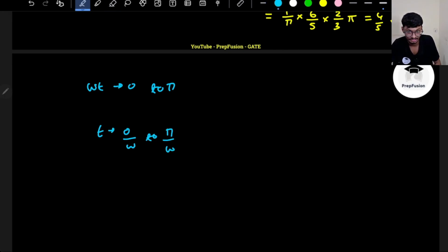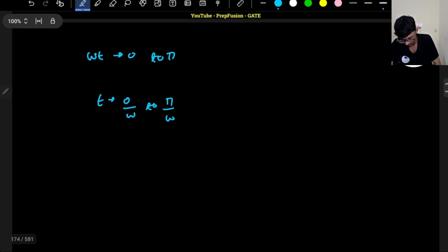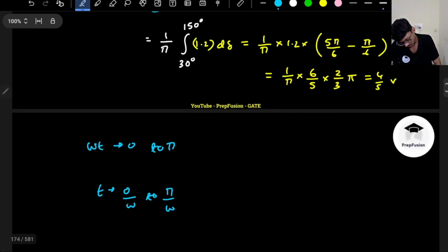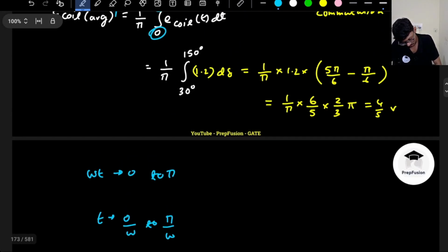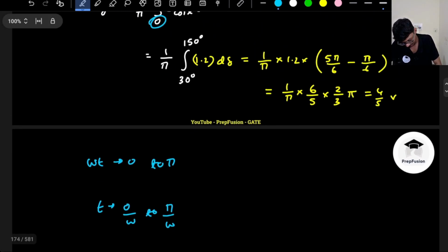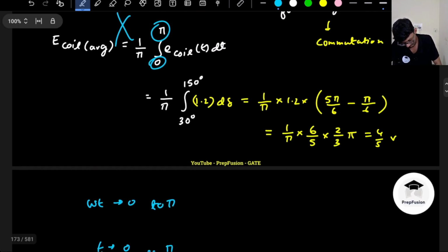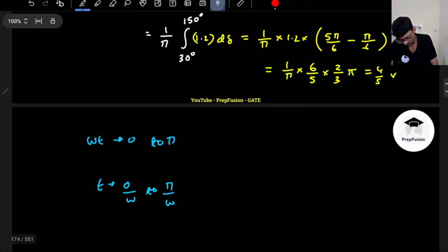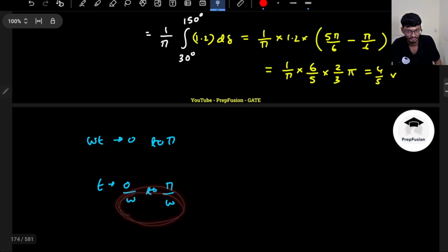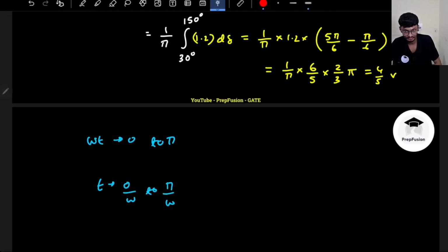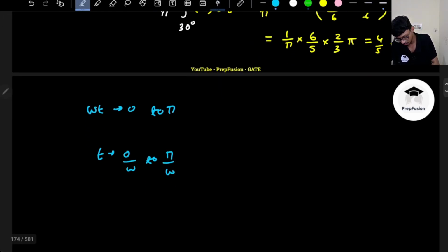So this omega is in electricals, remember? This omega is in electricals. Okay. Yes, omega is in electricals, yes. Okay, that is what I messed up actually. Now I don't know this omega frequency actually. I don't know this omega frequency. Okay, I know mechanical frequency, speed, right? So this is omega electrical. I know omega m. Omega m is given to me. Omega m is 2 pi n, the rotation of the armature divided by 60. Correct?